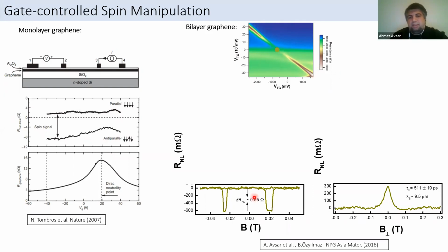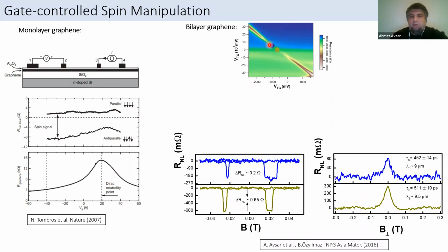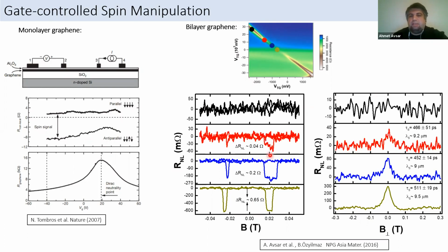So what was happening is that near zero electric field, we see regular spin transport and Hanle precession. And as you increase the displacement field, we could see that we can completely shut down the spin current. And it could work as a kind of spin switch effect in bilayer graphene. But this only works at low temperature, and it's partially because this material has an extremely low band gap. Okay, and if you want to really revise this kind of device concept,